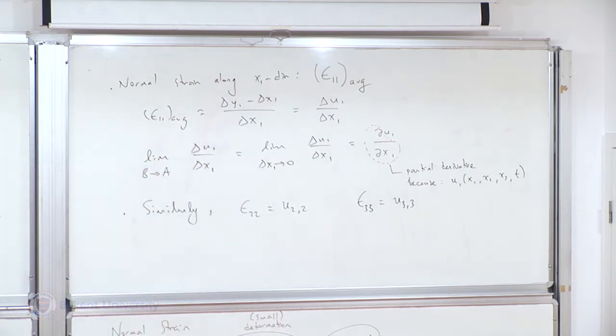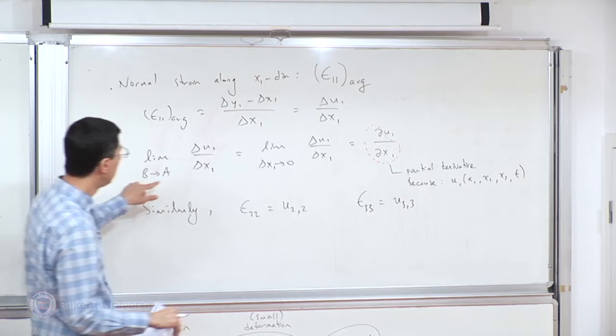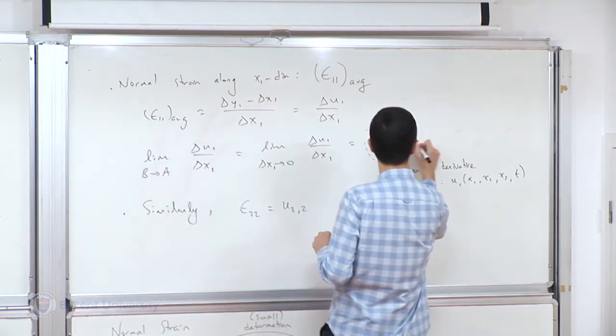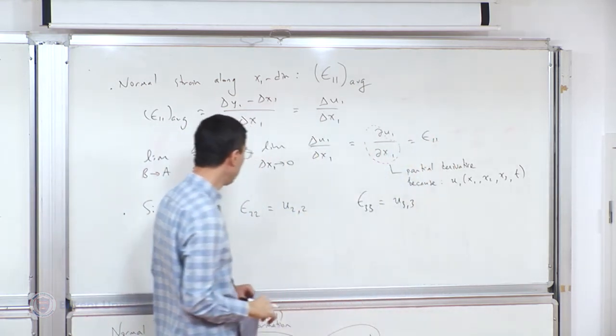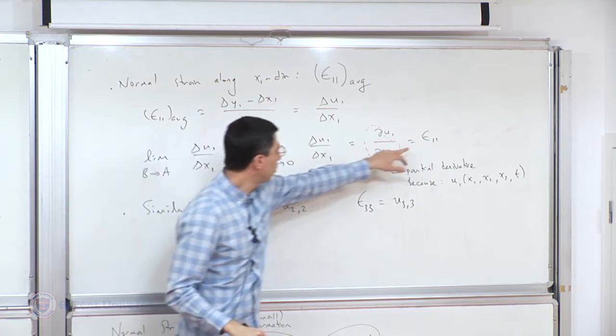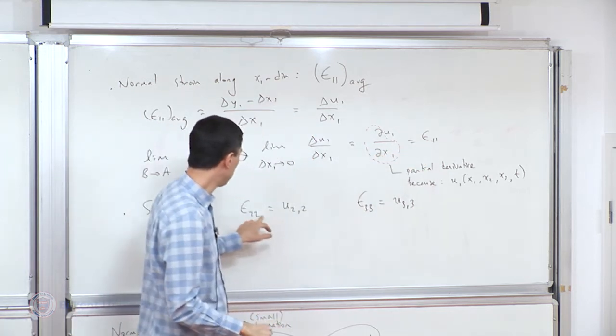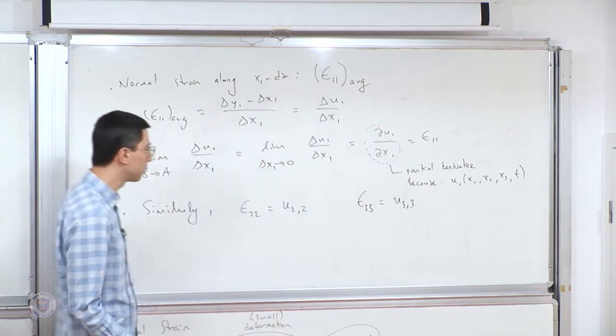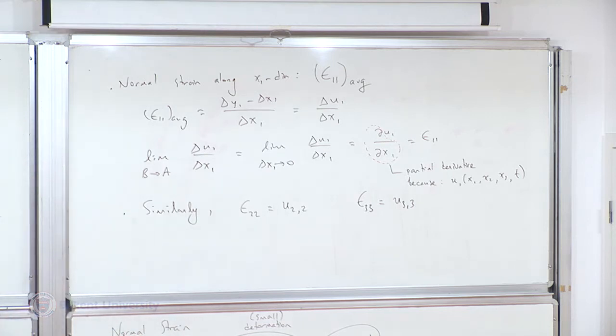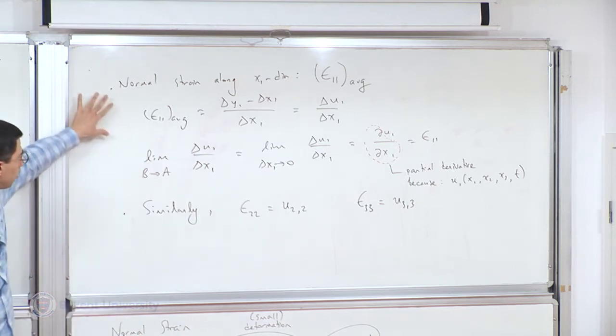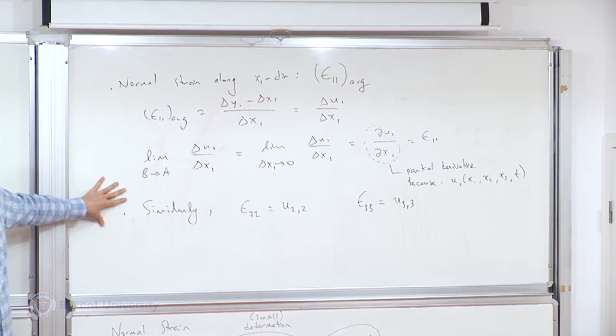So that is now a mathematical expression, a result that relates the displacement field, or the displacement vector as a function of position, explicitly to the strain components. And notice that is now epsilon 1,1. So these are all diagonal components, right? 1,1 component, 2,2 component, 3,3 component. Okay, so this part you knew. So in a sense, this part is new, right?